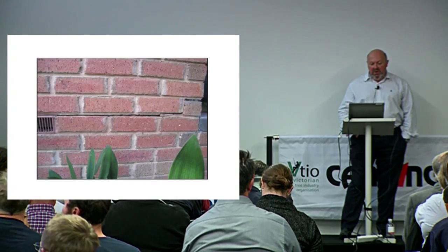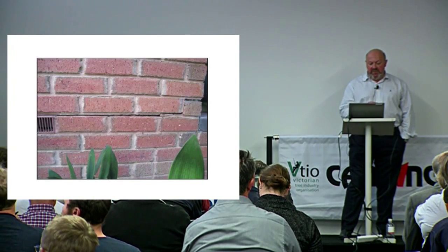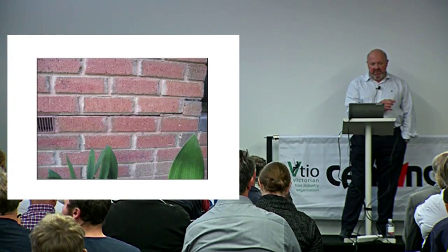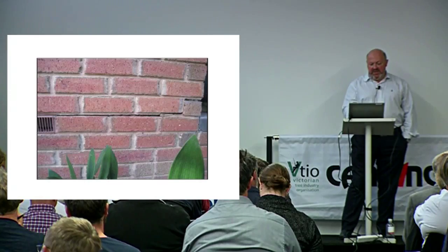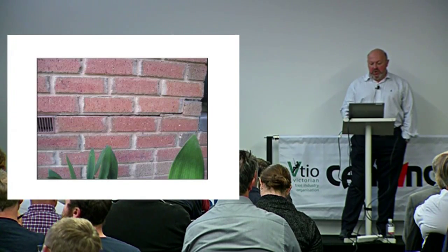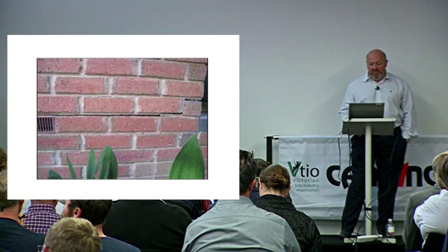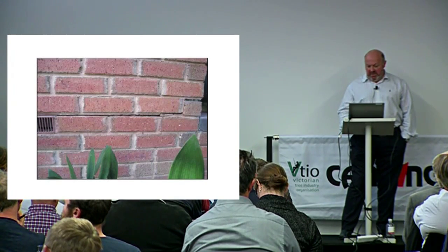So that's a typical photo of a house that's suffering from heave. Now the heave is occurring to the left of the photograph. So the section of building to the left of the photograph is moving upwards due to a leaking pipe. This section of the building, the soil moisture content is relatively stable, staying where it is, and because the next door piece of the building is going up, it's causing that brickwork to go into tension, which has caused the horizontal pattern of cracking. Really common cause where you've got excess moisture.